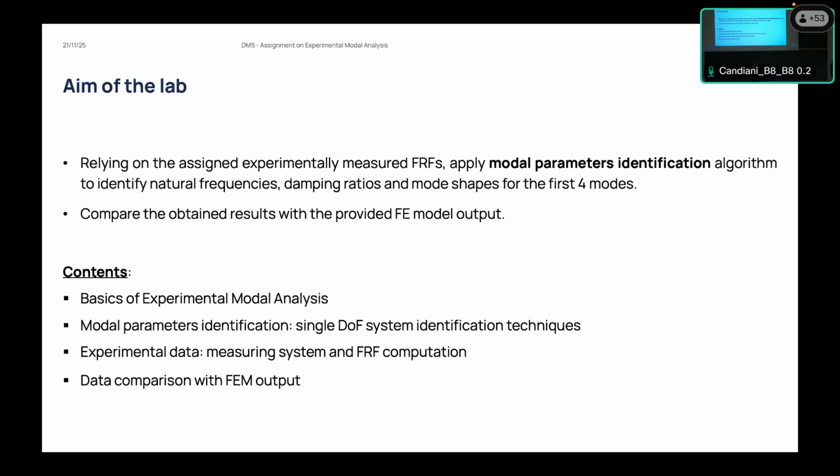So what we are going to do is to analyze some data that are representative of the motion or the vibration of an elastic model of a structure that is now under construction here in Milan, and that wind tunnel model was tested in our wind tunnel a couple of years ago. By analyzing those data, we can compare the modal parameters we have been able to estimate with the ones that are coming from the finite element model of the structure itself.